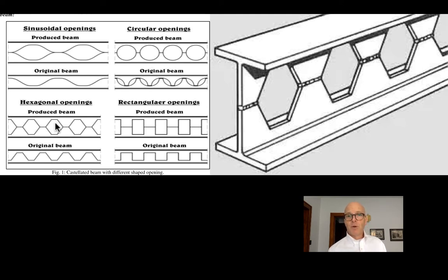We come back in and we weld those pieces together. Here we're welding the hexagonal tabs. So if you think about it, that piece of the beam before we cut it was sitting right there. We've sliced this hexagonal, zigzag shape through it. We've shifted the beam a little bit, and now all of a sudden we get basically free depth. And remember, depth is key.